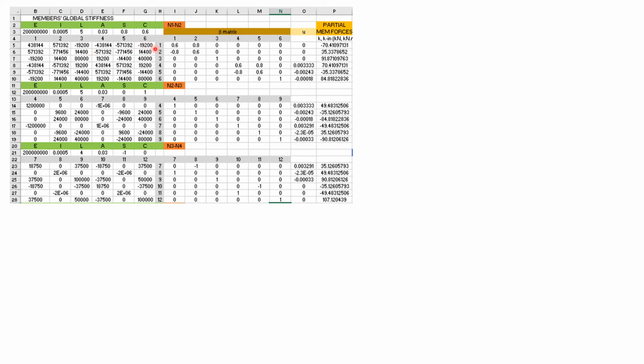Then the global stiffness matrix for member AD, or member 1, will be automatically generated because this is a matrix calculator. This is the beta matrix for that element AD. Then these global displacements are solved after the structural stiffness matrix together with the load, which is only 120, going to the right at 4.